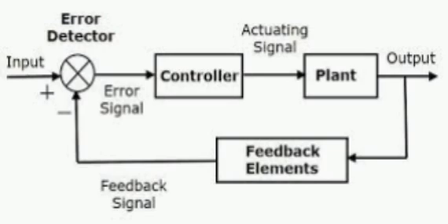Response to unit step input function, time response expression. Case 1: zeta less than 1, that is underdamped oscillations. c of t equal to 1 minus e power minus zeta omega n t by root of 1 minus zeta square, sin of omega d t plus phi, u of t, where phi equal to tan inverse of root over 1 minus zeta square by zeta. Response settles within 2% of the desired value of 1 unit, damping out the oscillations in a time of 4 tau, or 4 by zeta omega n.